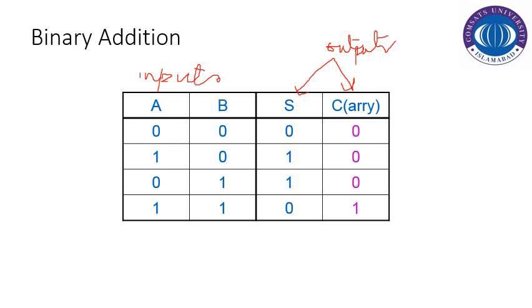Later on we will discuss how we extract the terms in order to specify the Boolean function from the truth table, when we discuss the canonical and standard forms of expression of the Boolean function. So in order to implement the carry operation, we just have to use a single AND gate, which is sufficient to produce the carry result for the 2-bit addition.